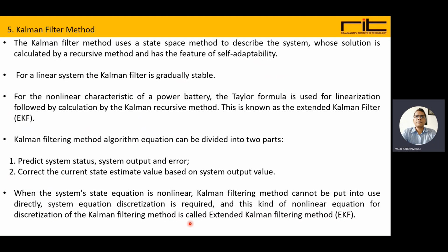The next method of SOC estimation is the Kalman filter method. The Kalman filter method uses a state space method to describe the system. The solution is calculated by a recursive method, and it has self-adaptability.